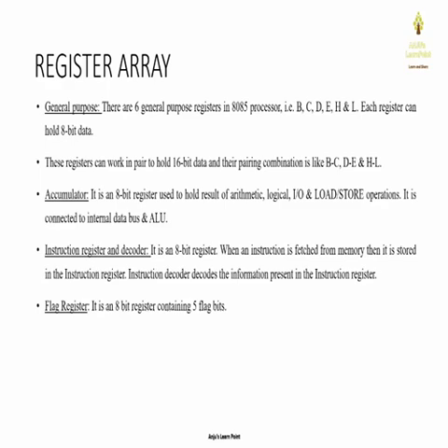The next component is the instruction register and decoder. It is an 8-bit register, and when an instruction is fetched from the memory, it is directly stored in the instruction register. The purpose of the decoder is to decode the information that is available in the instruction register. The last component is the flag register. It is also an 8-bit register having 5 flags, and these flag bits can take values 1 or 0 depending on the result of the operation that is stored in the accumulator. That is, the flag register reflects the status of the result stored in the accumulator.